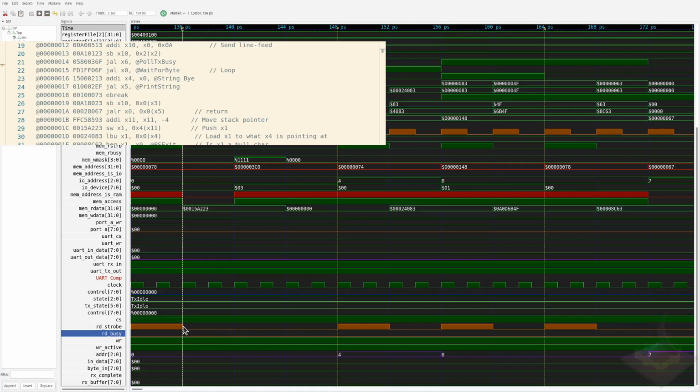Now in our case, the BRAM, the block RAM, is pretty fast. It doesn't have any real wait cycles when it comes to working on the FPGA. If you crank your clock up high enough, I think you'll start to violate some of the timing constraints, but we're pretty low. So in my case, the component just keeps the busy flag low. We're never busy. Whenever they want something, we've got it. And that's what this store word instruction is doing right here.